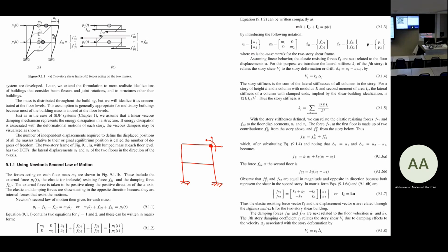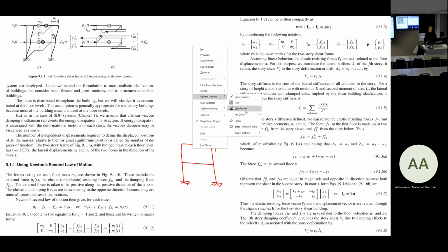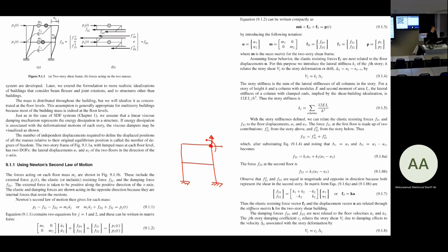first of all, we assume that the displacement along all the vertical degrees of freedom is 0. I mean these 4. The displacement along this one, this one, this one, this one, and these are obviously 0 because of the support. But those 4 are 0 as well.